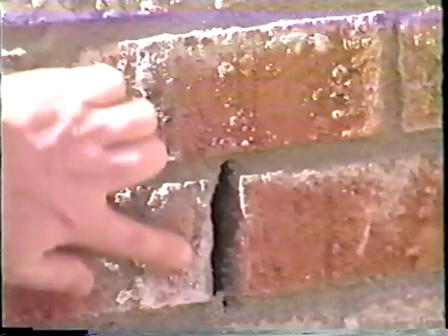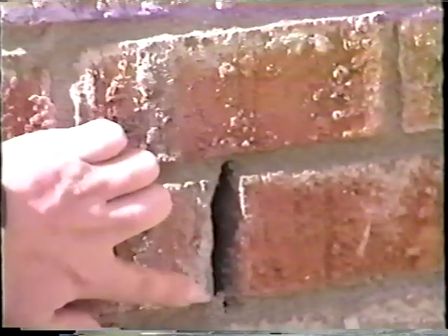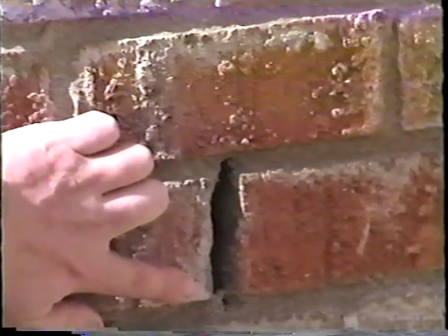The drainage wall must also have flashing and weep holes. Flashing and weep holes are located at the base of the wall, over windows and doors, and other interruptions in the airspace. If flashing is not installed, water which penetrates the brickwork will usually end up inside the house.